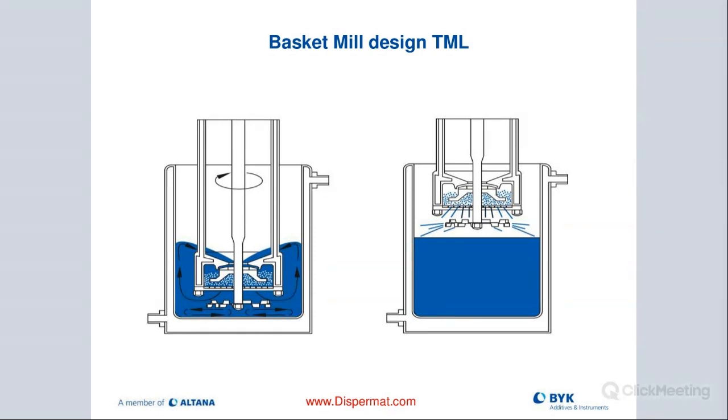This is a great example, a slide here, a graph that shows you the rotation and flow of the mill base through our basket mill. The Cowles blade on the bottom does a great job of drawing out the mill base and pushing it up around the container side, and then the pumping and stirring wheel we have on top draws it back in really nicely.